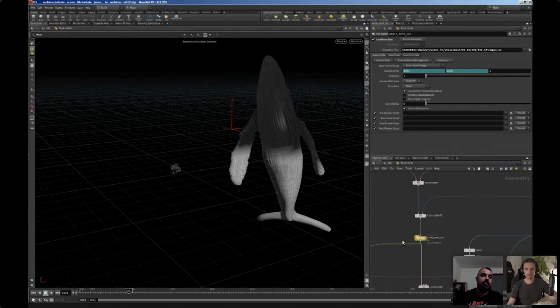So later on, even if our mesh is broken or we need to redo some part, we have the base VDB already done, because sometimes this VDB can take a few minutes. So why not cache every stage? Even if you need to redo something, it's a lot easier than going all the way back, and easier on a farm.